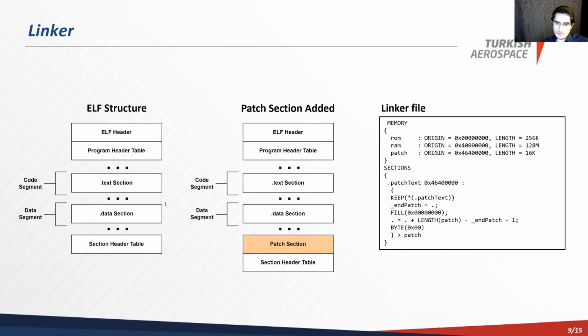And like I said, we need to add a patch section to our ELF structure, like you can see over here, this orange area. And we achieved this by modifying our linker file, which you can see a part of over here. Yeah, that's how we achieve this.